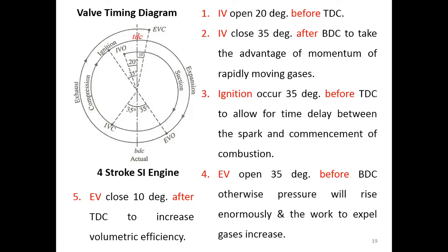And the most preferable position for the combustion to take place is at the top dead center. But it is seldom that we have it at the top dead center. We normally have it before, because we want the combustion to happen before here. Why? Because we want the pressure inside the combustion chamber, or the cylinder, to have time to reach the maximum pressure when it is at the top dead center. This is the key point.